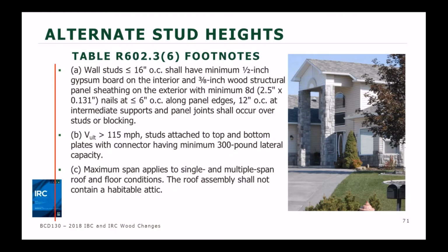So that's, again, a gray area that we have that doesn't really say, okay, what's my minimum sheathing need to be? And so you need to go to other sections of the code, like section 602.3(3), that is referenced in wall bracing, that has a minimum nailing pattern and stud spacing for various wind speeds.